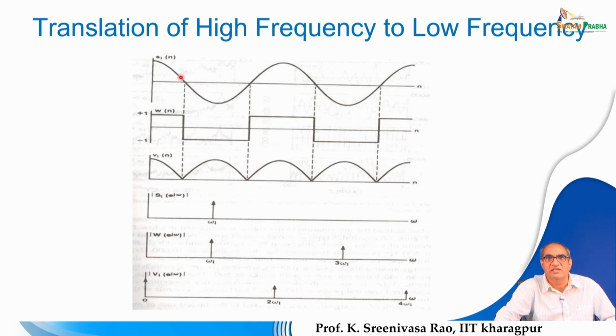because the sinusoidal signal has both positive and negative content, and by multiplying this signal with this rectangular pulse train, you can convert the sinusoidal to a fully rectified signal, so full wave rectification is obtained. This process, we are performing the multiplication in the time domain. We will see what happens by applying a nonlinearity in the frequency domain.